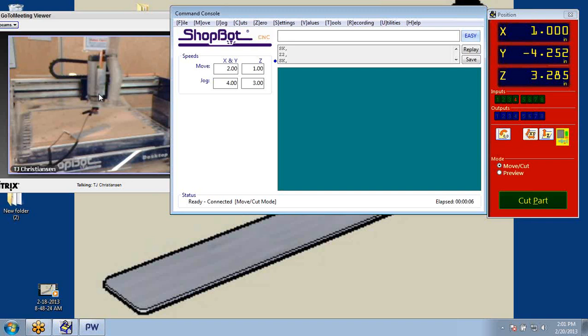If I've got this humped board or humped table and I put my material on it to cut, it's only going to be as flat as the table, which could be not square anymore to the machine because it's bowed up. Or if you're a very avid cutter and you've cut your machine surface and got all that brown spoil board just chewed up, you want to flatten it by what we're about to do. Get it to a nice, flat surface.